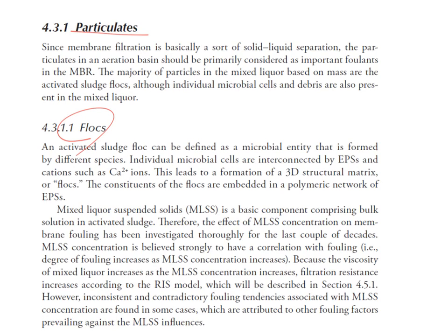So the fouling tendencies associated with MLSS concentration are inconsistent and sometimes contradictory. That means there are other factors affecting membrane fouling in the MBR system.